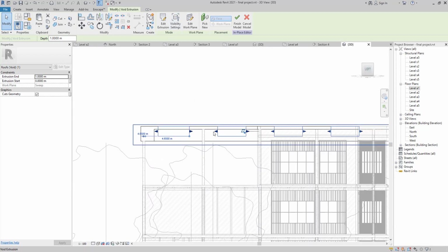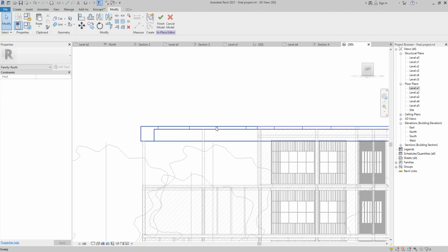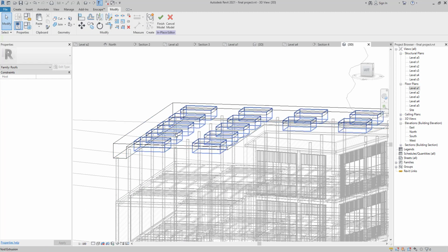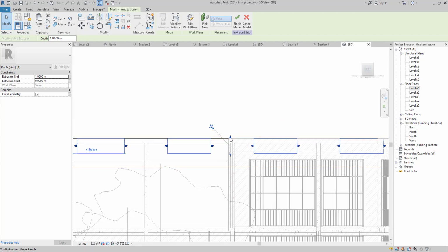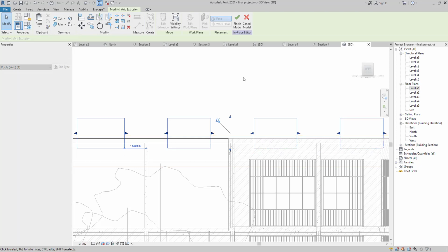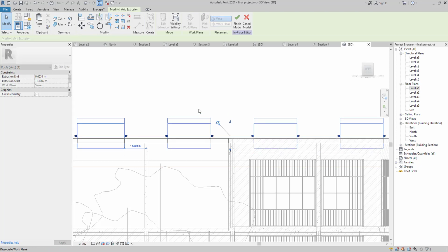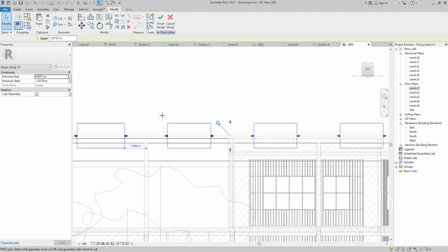So right now you want to move your void with arrow. So for accessing the arrow, you can just click one time in your screen, and after that go pick your void, again come back, your arrow will be here, and we are just going to pick it up like this, and then we are going to select cut.